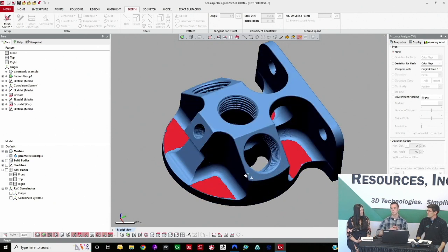But if you're doing the side of a boat, a very highly organic fiberglass shape that you need to extend the edges of, and you just want to surface one side of it, and you're going to be doing a lot of direct mesh editing, then it would be highly recommended to make a copy of the mesh, so you weren't deleting data out of the original.